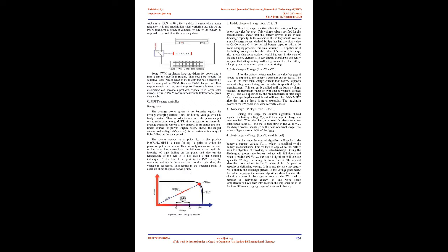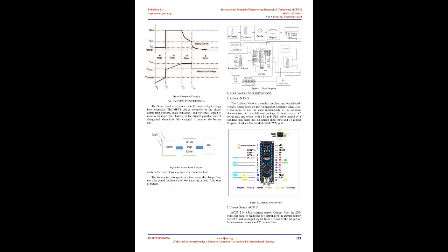The group of batteries selected should have the same capacity. If the batteries have different capacities, the charging will have to be set according to the lowest capacity. C. Mixed constant current/constant voltage charging method.